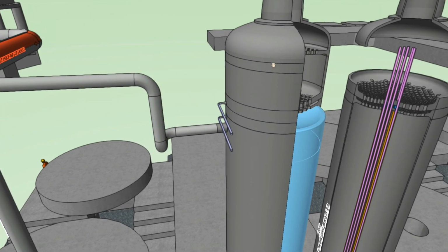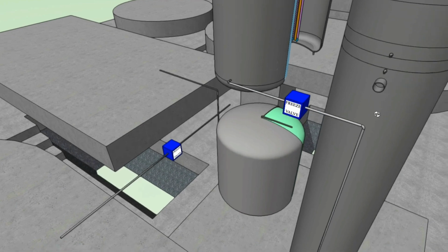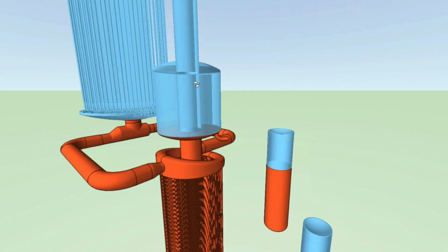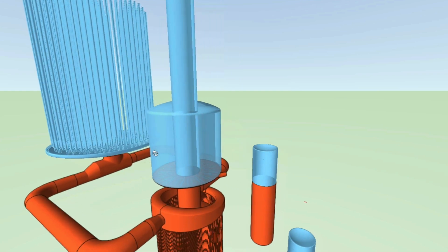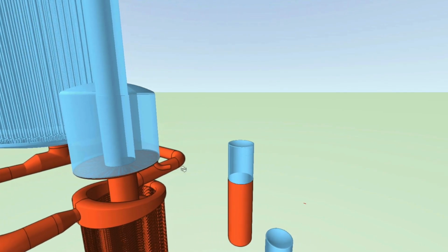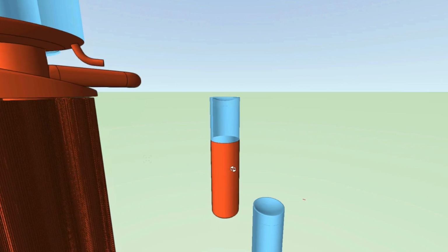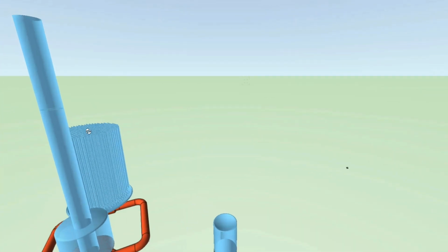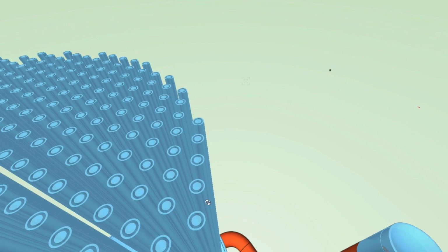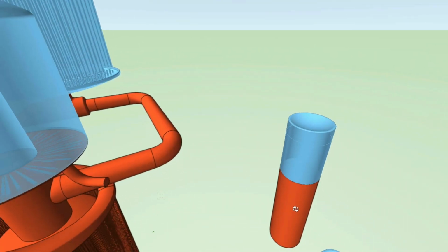This higher drain tank is separated from this drain tank with the freeze valve. So when this pump shuts off, all the fuel that was held above it will then flood into here, flood up in this valve, come over to this drain tank, and it will only fill this much of the drain tank. The reason this looks bigger is because this is mostly space. Okay? When that's all condensed, this orange here is the same volume.